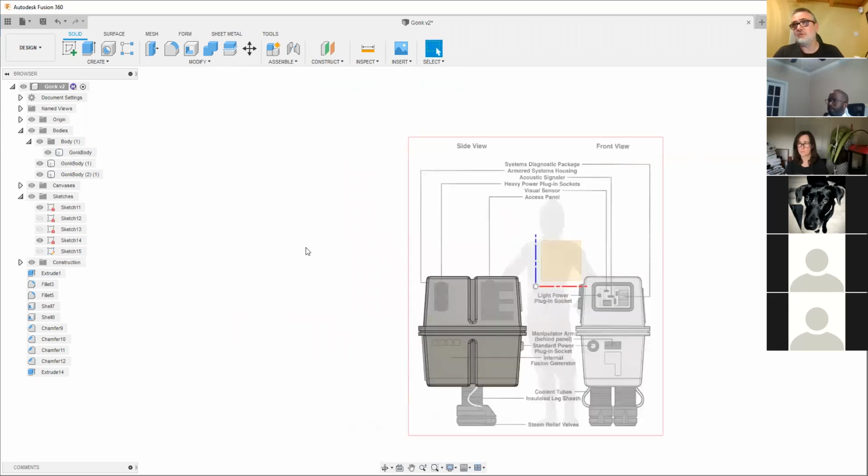It's really just tolerances. If you've got 2 pieces of plastic that fit together like a dovetail or something like that, I typically use a 0.2 millimeter gap between the faces, so that it's a nice solid tight fit. You can move between 0.2 and 0.35 when you're looking at plastic to plastic. These are really ones that you build up by experience and testing. The challenge is that every printer prints very slightly different in the way that it squishes, etc. So I tend to err on the side of slightly looser so that it works for everybody.